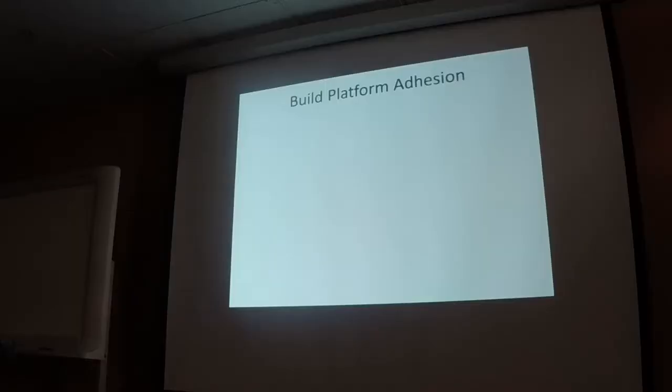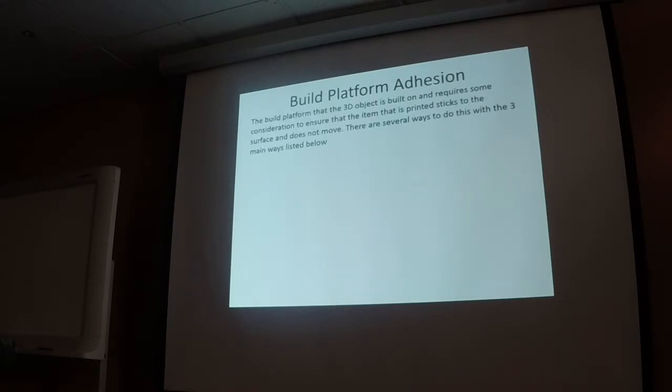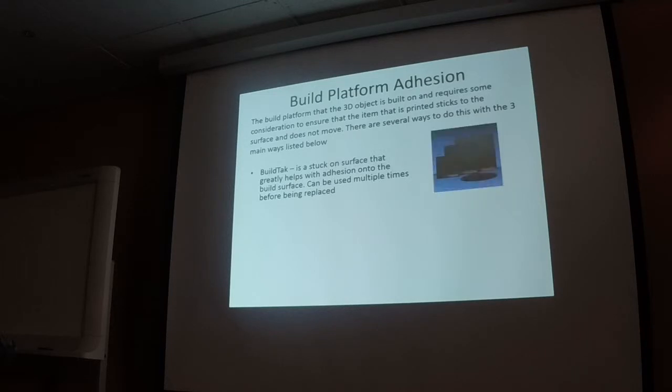Build platform adhesion is one of the most important things, because if you haven't got that right, you end up with a mess. It becomes very frustrating. So I use a thing called build tack.